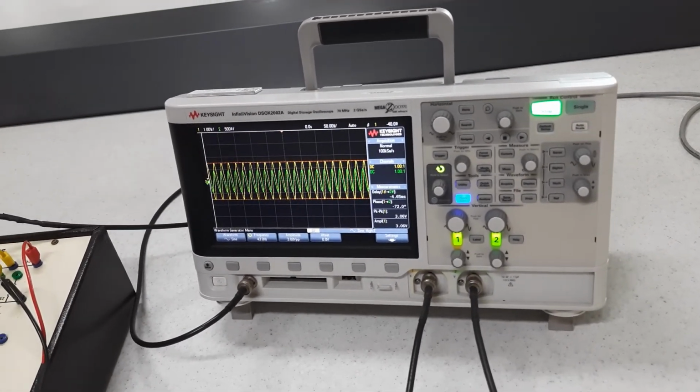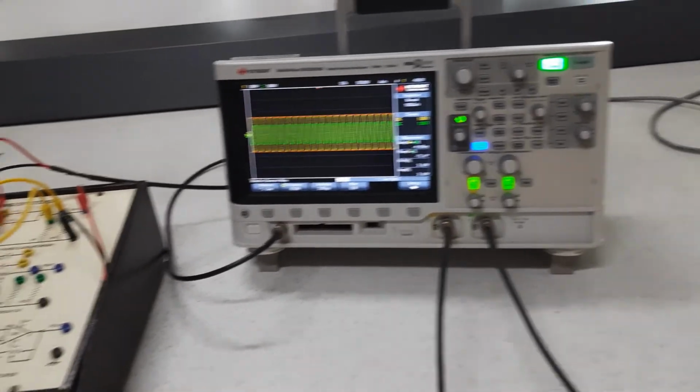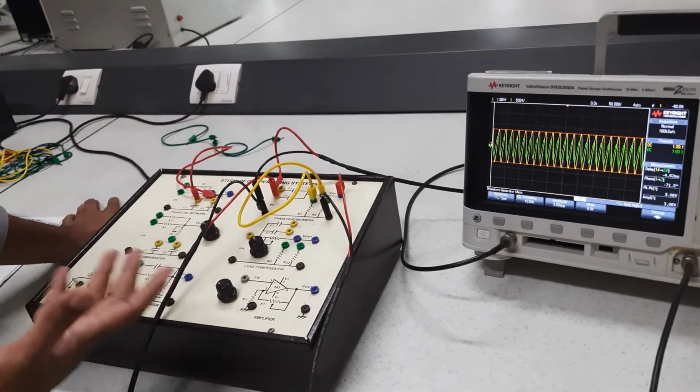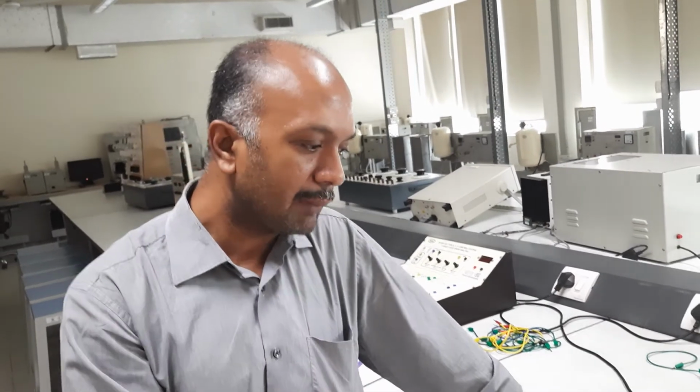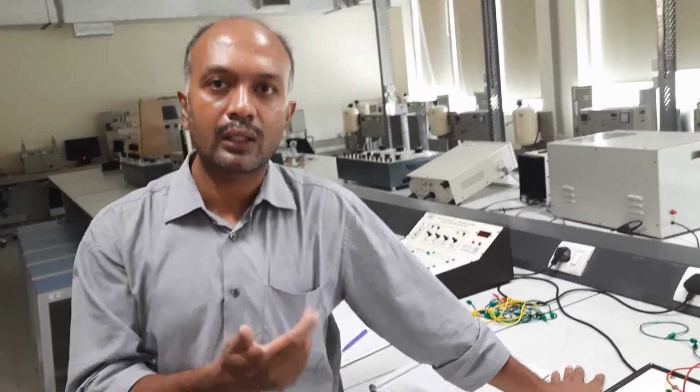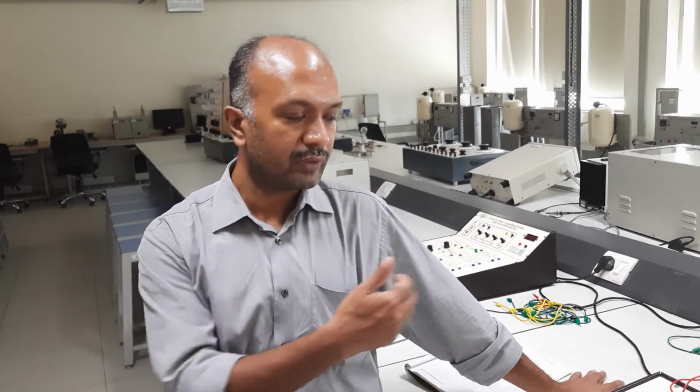Why they are getting clipped is because all those implemented behind this board are based on operational amplifiers, and these operational amplifiers, you know, have a saturation level based on the biasing voltages. Right, for an operational amplifier, the biasing voltages will be plus 15 or minus 15. So if you give your amplitude beyond plus 15 or minus 15, then your output is going to be saturated. But it is always better that we keep our amplitude close to 3 volts peak to peak, and we repeat the experiments, as I said, for the phase lag network.